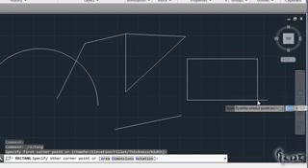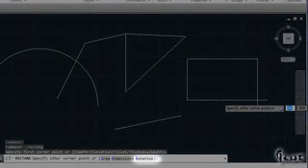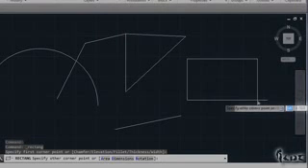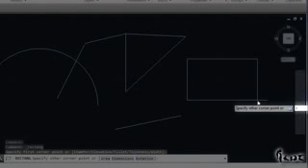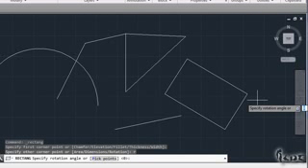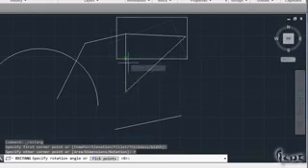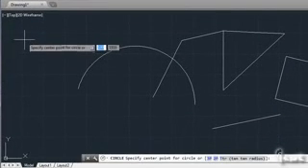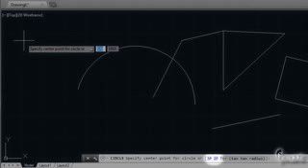This is used to type a command. If the command Rotation has the blue letter R below, it means that you need to type R in such white slot to run it. Press then the Enter key to enter the command. Make sure to pay attention to this, because for some commands you need to type more than one letter.